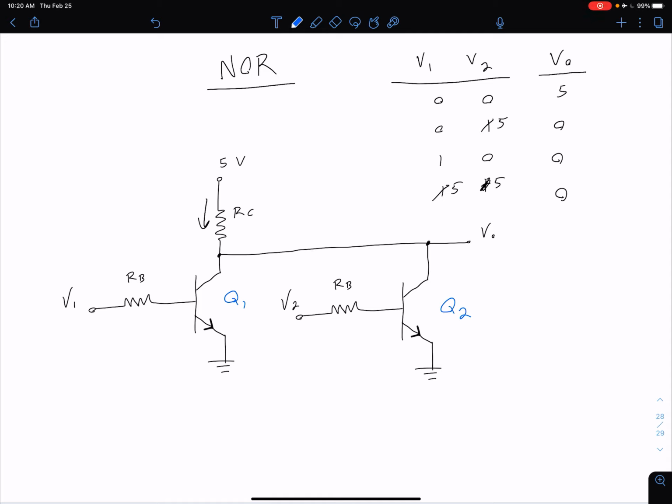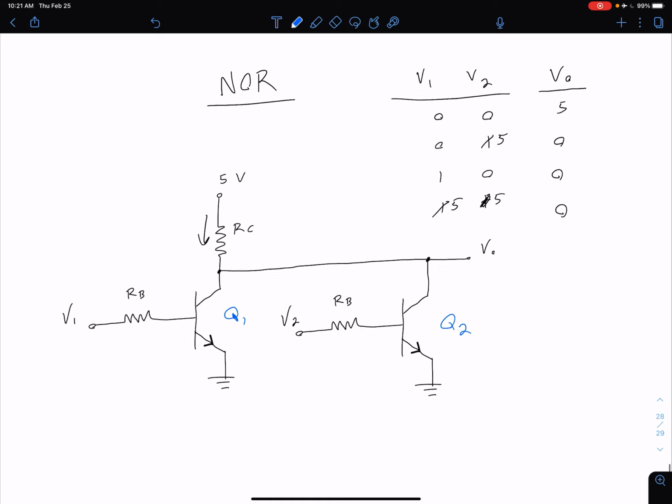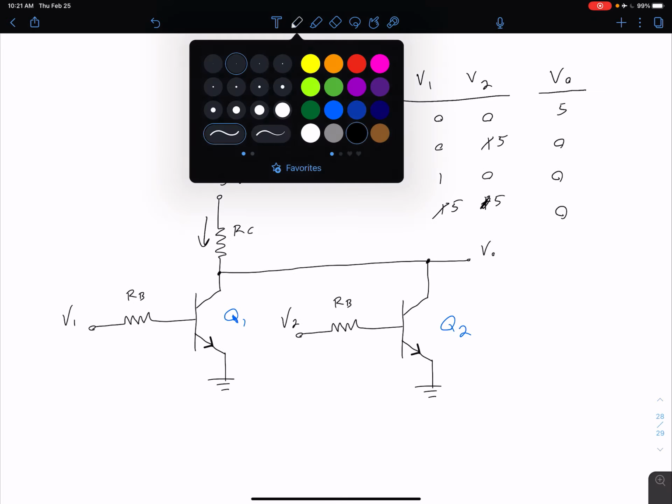And so the letter that we use for our transistors is typically going to be Q. The reason that we don't use T is because T is oftentimes used to refer to transformers, and the Q comes from some of the early packaging of our transistors, which if you look at it from an aerial view, looks like a little Q because there was a little notch on a circular or cylindrical casing. So that's where that comes from. So again, it's important to label those if we have multiple transistors in one circuit.